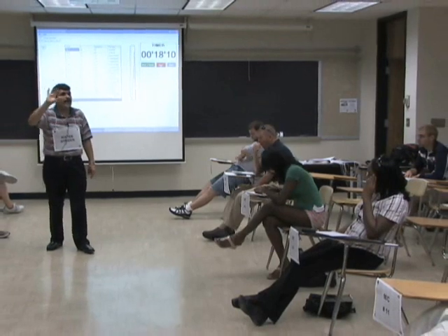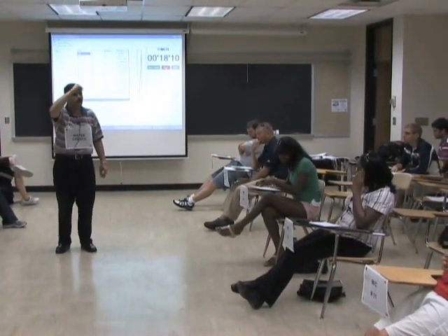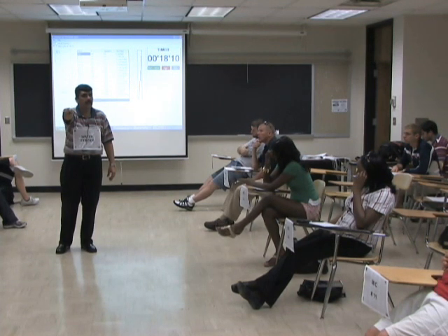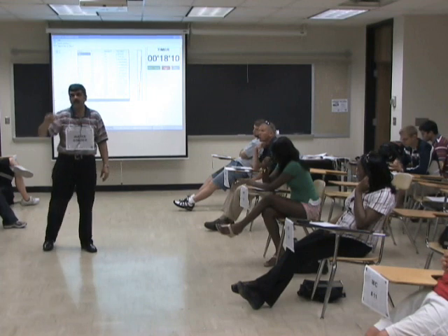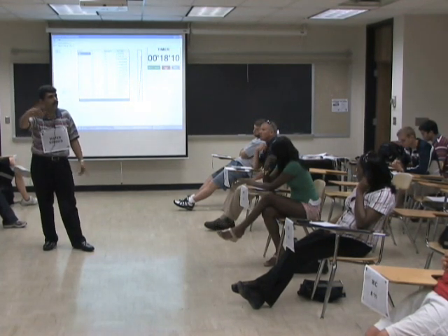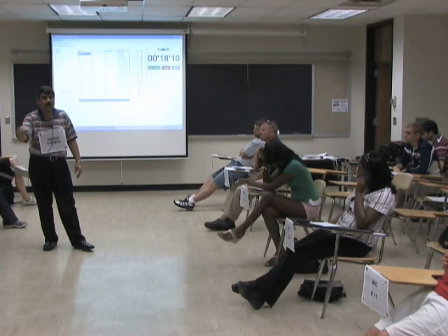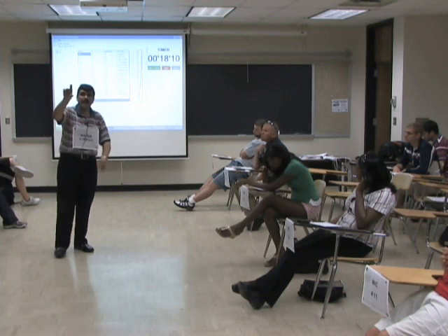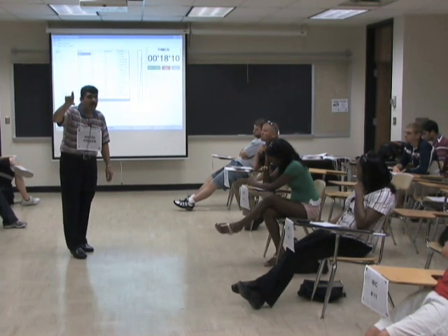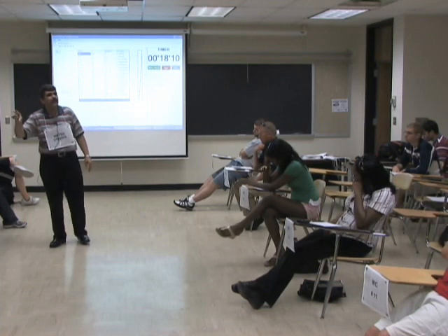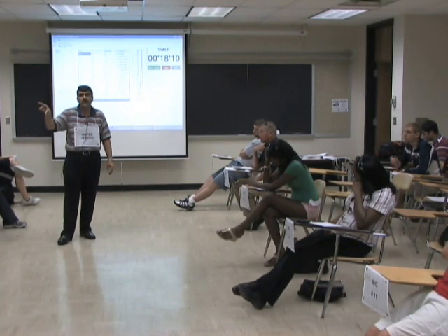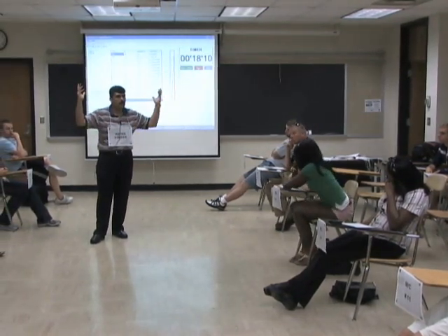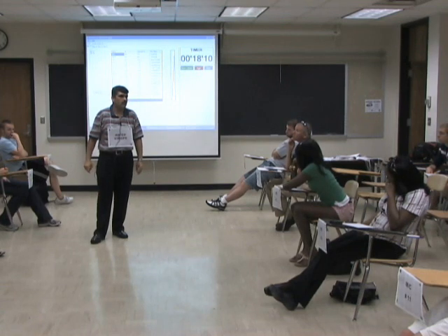Why do you think that people talk about andon lights? If you go to Honda, they'll have a little display: today's schedule, which is the number of cars, and where we are at today. It's a simple gap analysis. Where we expect to be, where we are. And they know immediately where the entire line stands. But that's because in assembly, it's a paced system. So really, the takt time is all that meter needs to capture. You don't have that luxury in a lot of factories, because assembly is not relevant or prevalent in all the factories across the world. But again, there, no schedule, so completely opportunistic approach to our work.